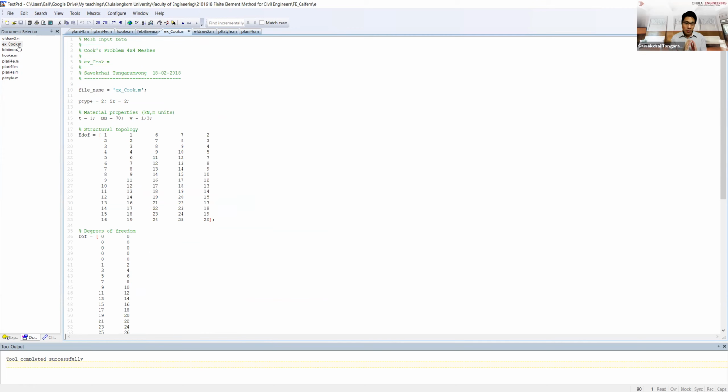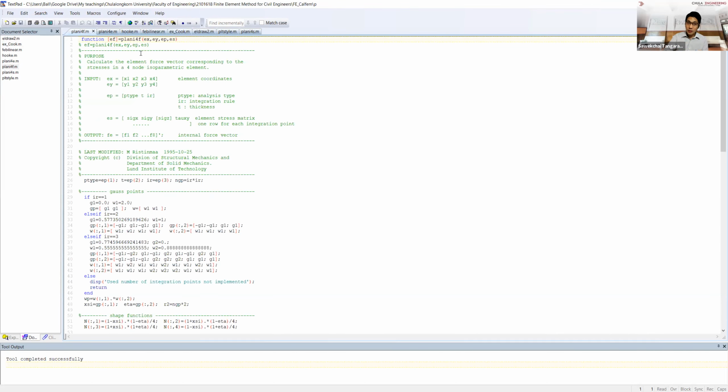You need, more or less, an irregular mesh, which is a non-uniform mesh, refined toward the bottom at the support. And you need to get the resisting force as the body weight of the dam, of the concrete dam, right? The formulation that I just told you is also in this code. You can use this code to generate the body force for you.